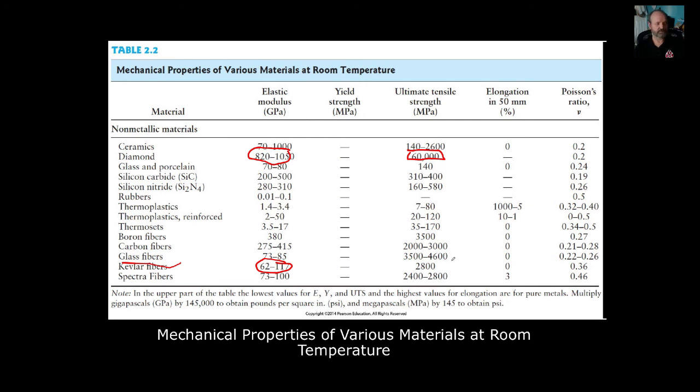That's when it starts to permanently change shape, and that's really hard to test. It usually will snap and fracture. So sometimes the curve doesn't even curve over. It comes up and then it breaks for brittle materials. Right? You never get to the point of plastic deformation. It just snaps. Okay, and then Poisson's ratio we're going to talk about a little bit later.